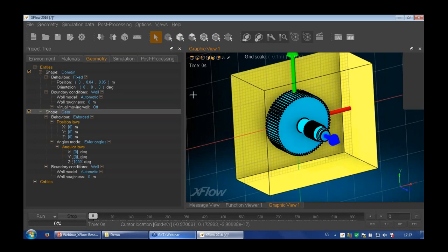So I'm going to define, for example, 1000 RPM, revolutions per minute, but I need to define that as a function of degrees, which means 360 degrees for one revolution, and per second I will divide by 60. Then I multiply by t, and this gives me my law in degrees, so I've got 1000 RPM in that case.